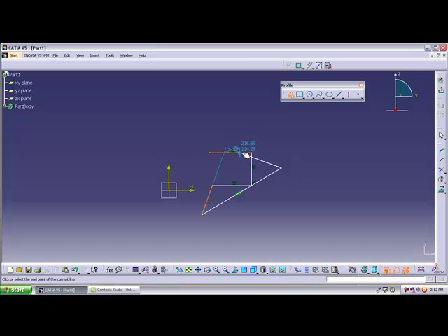It means when you are drawing the sketch, these constraints are all automatically created. If you want a constraint, click and it is applied. If you don't need the constraint, because sometimes it disturbs our profile, then hold the Shift button. By holding Shift, you don't get any constraints, meaning they are not highlighted. Then you can draw exactly the shape you want.